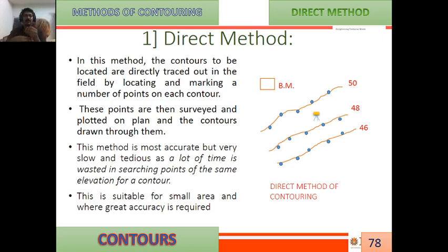So it is a tedious process, that we have to keep on moving the leveling staff until we get the same reading. Say if we require 1.48 meter to be the staff reading, it means the line of sight must coincide with 1.48 at that point. Wherever the point is, we have to move by trial and error and hold properly.